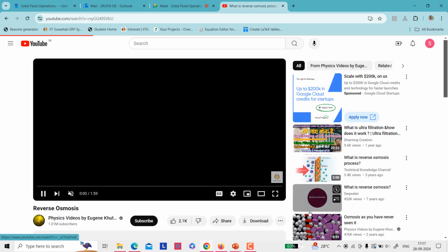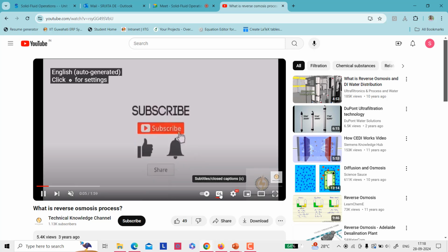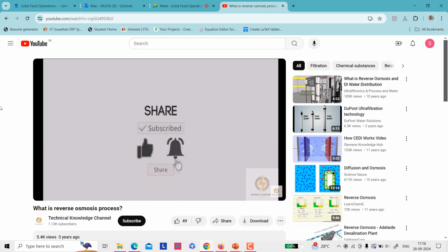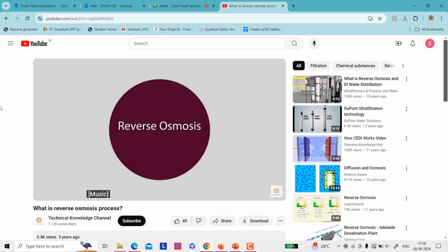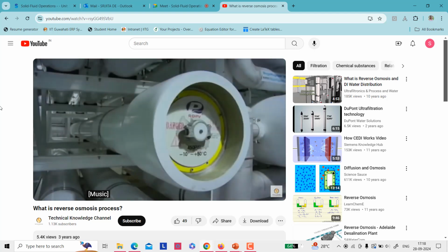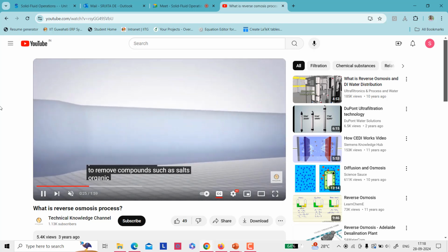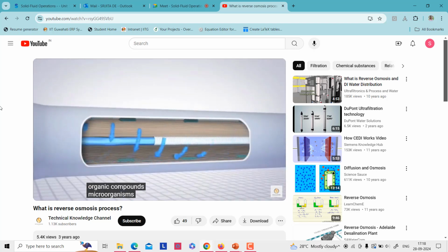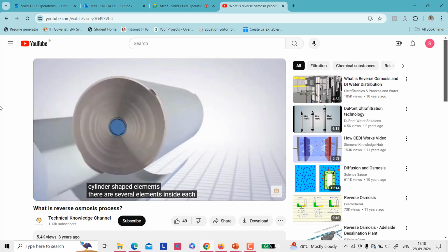Two streams of water are produced: pure clean water, or permeate, across the membrane sheets passes through the membrane layers to the inside tube. Water that does not permeate becomes more highly concentrated with salts and other substances. This water is called concentrate. Water flows out of the pressure vessel, and the concentrate flows out another outlet.